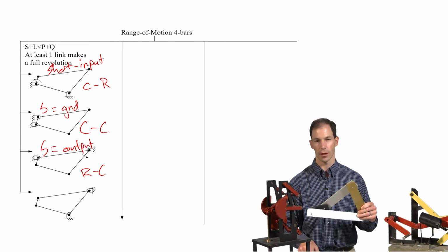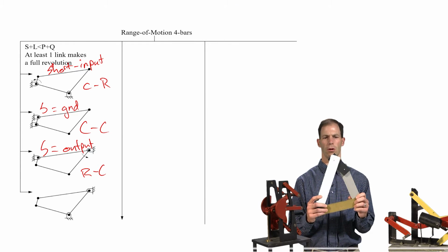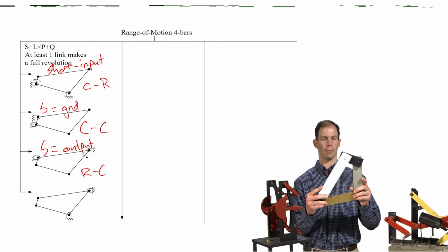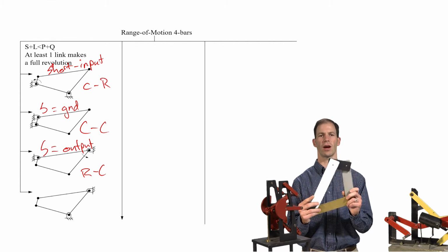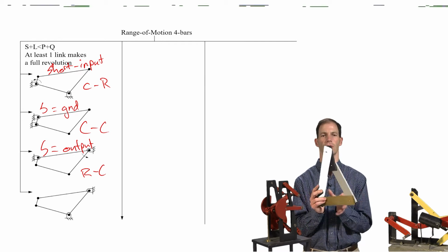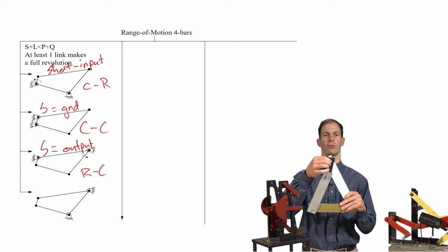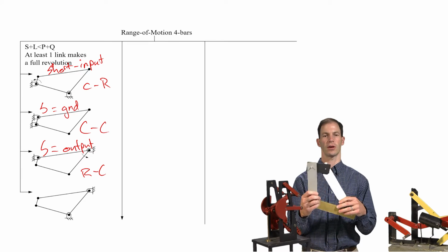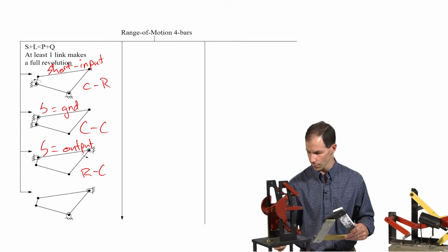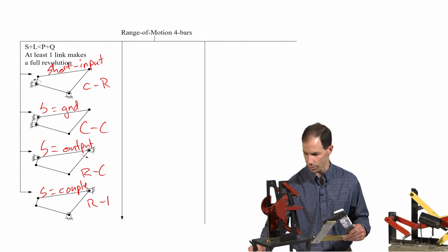And finally, I can then move to the point where my shortest link is the coupler itself. And you might say, well, wait a minute. Both my input link and my output link no longer rotate, they only rock back and forth. Why is this a Grashof mechanism? Well, you'll notice my continuous revolution is now up at the coupler. And I could, if I wanted to, place a motor between these two links. And this is still a Grashof mechanism, and we call this a Grashof rocker-rocker. So my shortest link is the coupler, and in this case, I have a Grashof rocker-rocker.